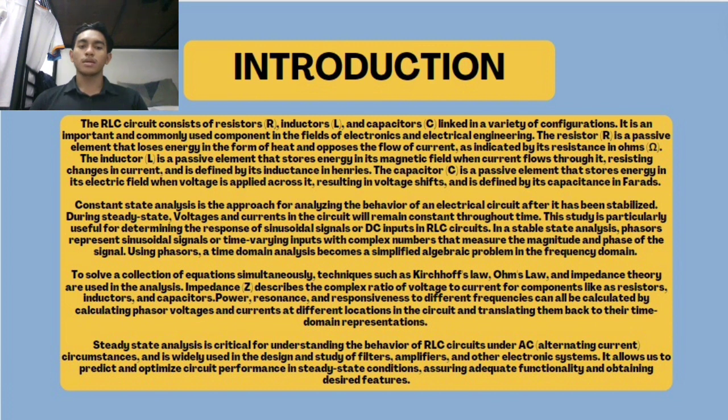Steady state analysis is the approach for analyzing the behavior of an electrical circuit after it has stabilized. During steady state, voltage and current in the circuit will remain constant throughout time. This study is particularly useful for determining the response to a sinusoidal signal or DC input in an RLC circuit. In a steady state analysis, a phasor represents a sinusoidal signal or time-varying input with a complex number that measures the magnitude and phase of the signal. Using phasors, a time domain analysis becomes a simplified algebra problem in the frequency domain.